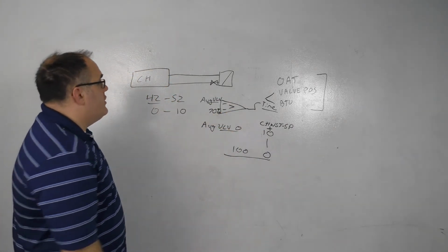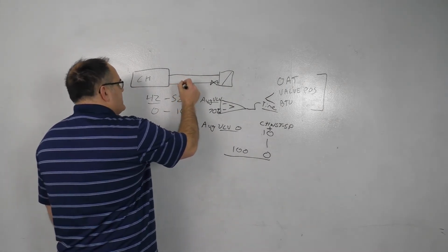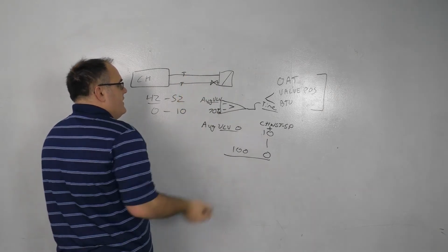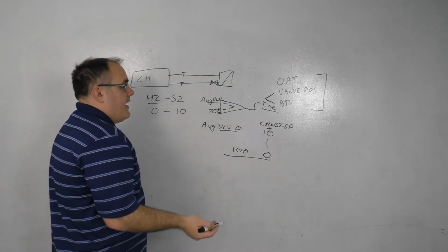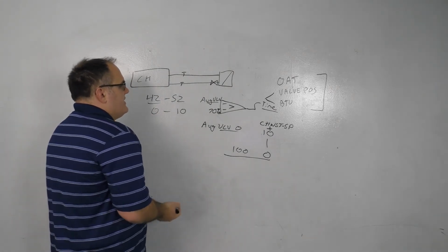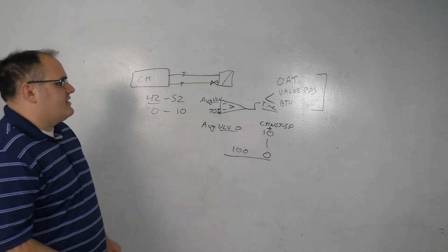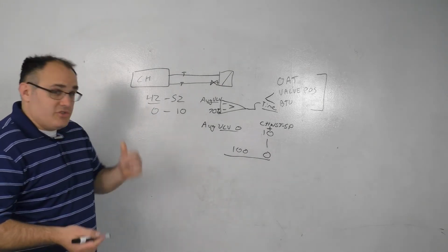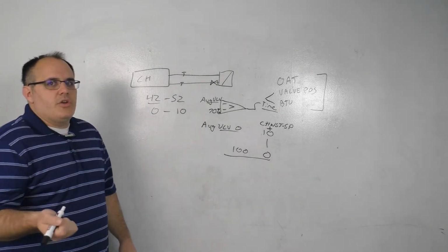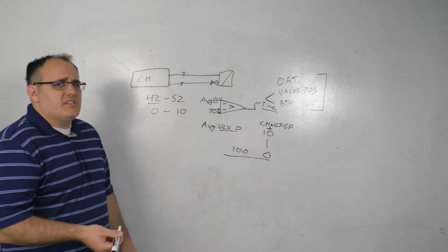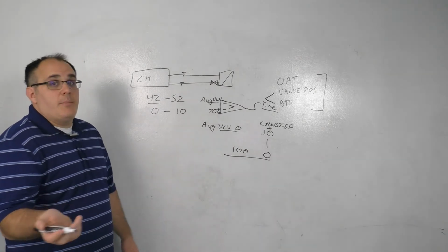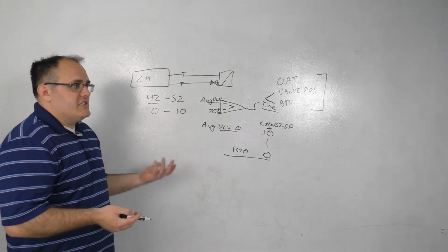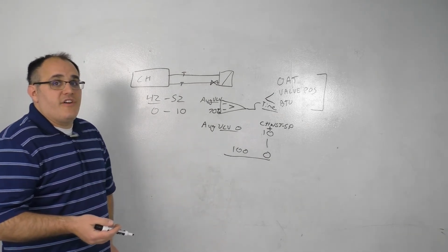And then finally, BTU is where you take delta T, so you take your temperature sensor, your temperature difference between supply and return, that's your delta T, so return minus supply, times your flow, times I think 500 if I remember correctly. That's your BTU calculation. And then you convert your BTUs to tons, which I don't remember the calculation off the top of my head, but you can go to engineertoolbox.com or just Google BTU to ton, and there's a calculator right there. There's no reason to memorize this stuff anymore, folks, because with your phone or just with your computer, you can easily go and find the answer.